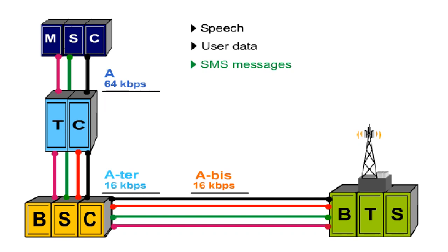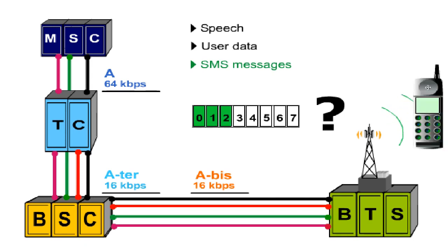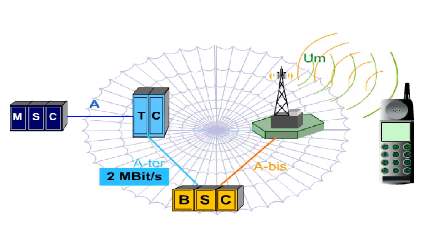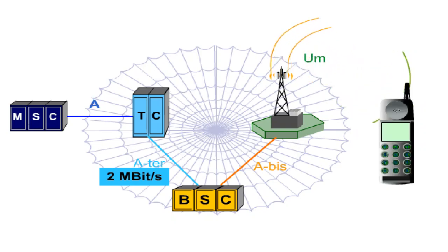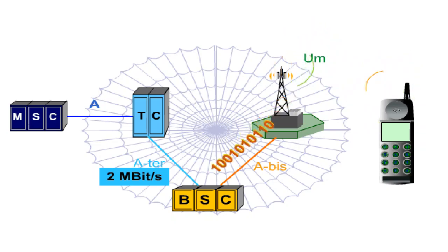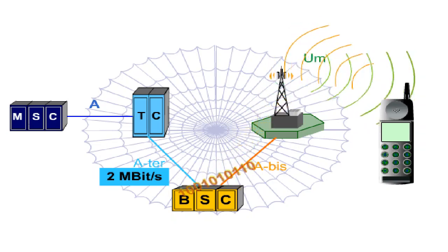The number of physical time slots that's available for the transmission of signaling information over the air interface depends on the configuration and is up to the manufacturer or to the operator. Within mobile radio networks, data is transmitted over PCM lines at a bitrate of 2 megabits per second. Air transmission is used between the mobile station and the BTS, and the information transmitted over the air interface must be adjusted to the PCM line so it can pass through the rest of the network.